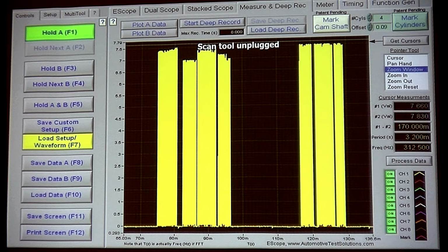Well, if you don't go to ground, the system can't operate properly because the threshold is programmed. In other words, when you're programming something, you tell it you're looking for this edge, a rising edge, at a voltage threshold. You know how you set a trigger up on a scope? You set the trigger, so you say it's a rising or a falling edge, and you say a value. Well, when you program, you've got to do the exact same thing, guys. The computer won't do anything until it's told exactly what to do.